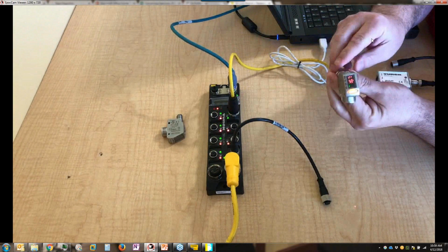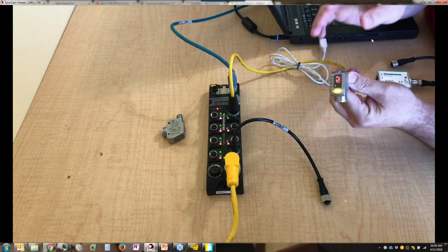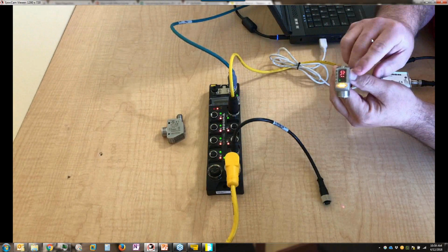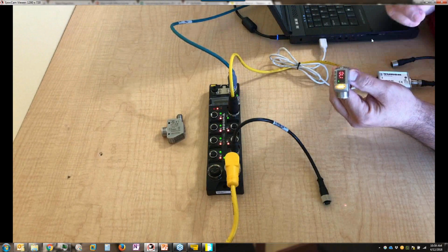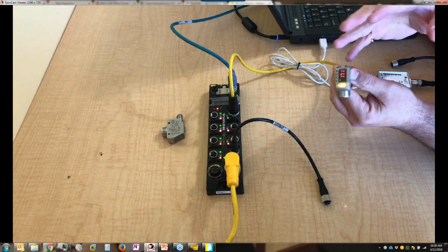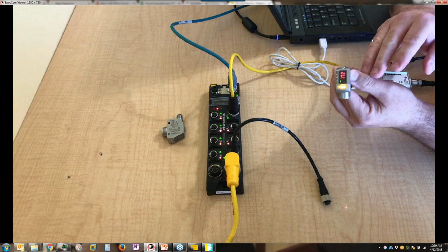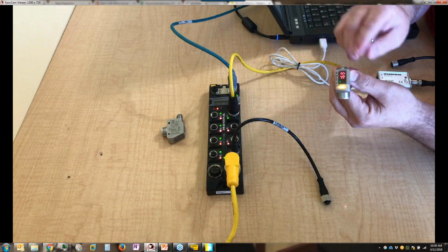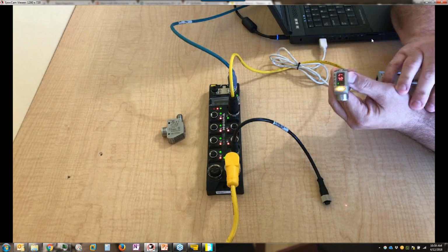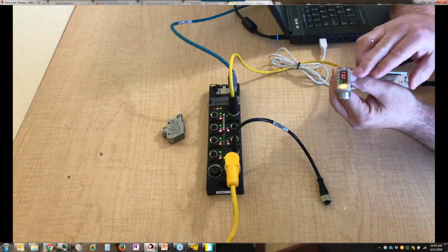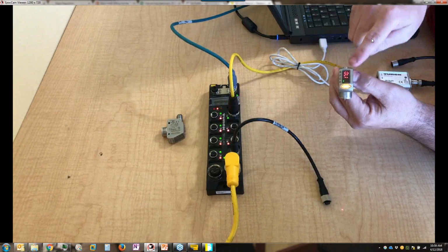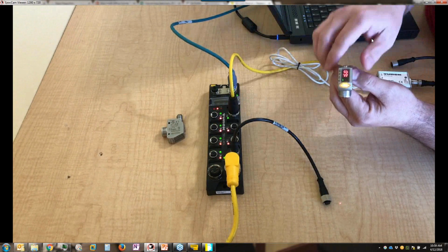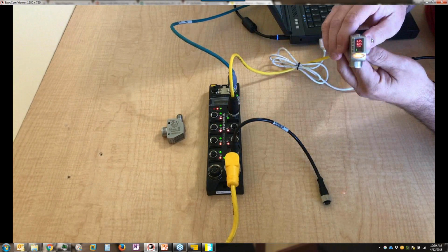Essentially what happens is there's a bit on the sensor, on the IO-Link device, that's, I believe it's called DS upload or DS flag, one of the two. And the bit's either low or high. So the master is always checking, when a device is connected, the status of that bit and determines based on the status of that bit if it's going to do a backup or a restore. So this did a restore, and that's why we're reading at 200 millimeters.